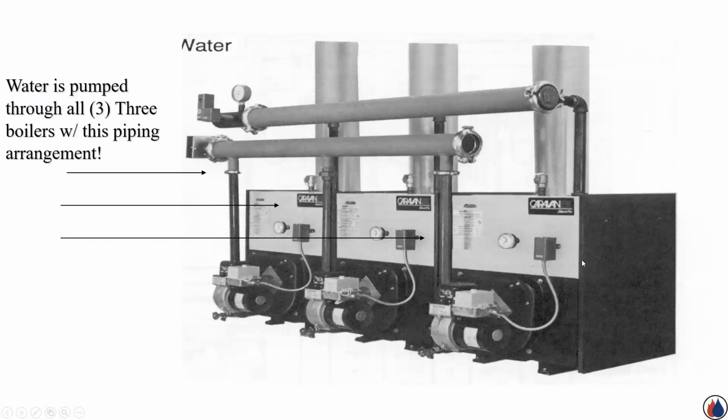And again, old technology, it's all over downtown Boston. It's slowly being replaced as we get opportunities, funding, new owners, whatever the case may be. But this is a quick example of a 3-boiler modular system where maybe only one boiler fires to satisfy the load, but I've got flow going through all 3 boilers. So these 2 off boilers become radiators. Very inefficient. You know, and they might be using a stager control. They might be doing aquastat settings that dictate when I come on, when I come off.